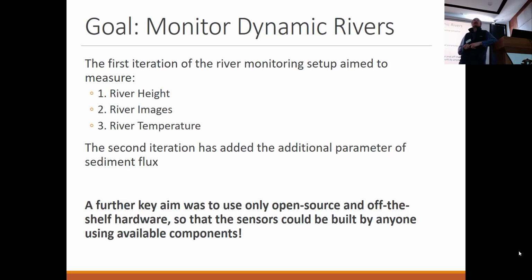So when you have these turbines spinning super fast and there's really hard sand going in there, you can destroy those turbines really fast. So having an idea of how much sediment you have at different times of the year, or having some warning of there's going to be a bunch of sediment coming in the next few hours, that can also help to change how the plants are run. And also to think about how much sediment they should expect to be infilling some of these dams.